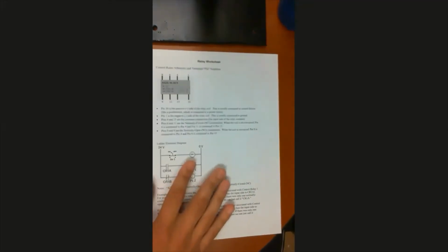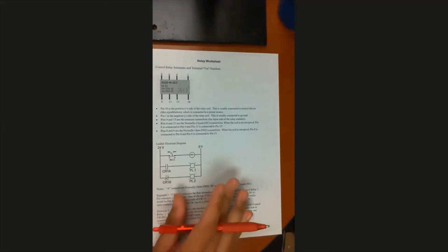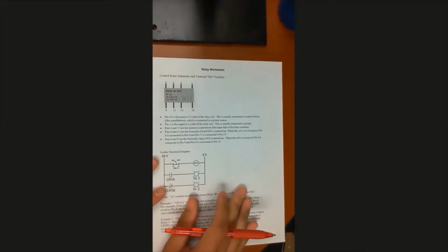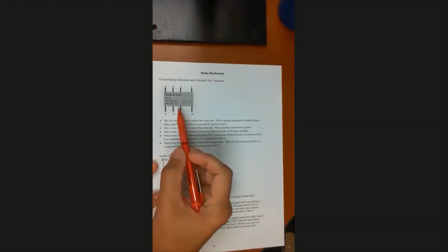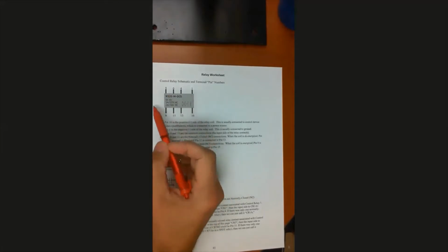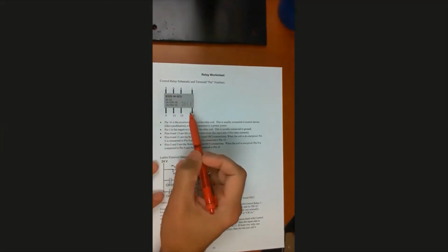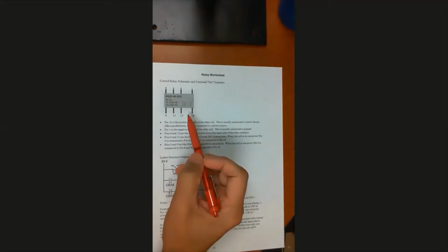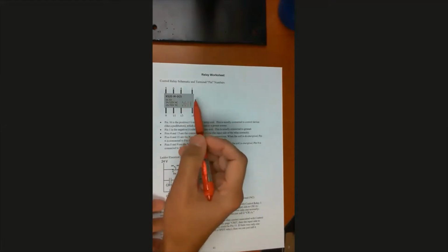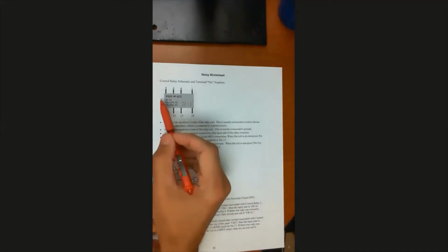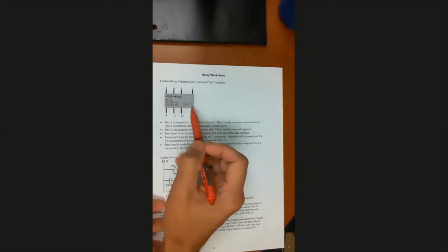All right, so this is page 41 of your lab manual. And the first thing that we need to make sure we're familiar with is the double pole, double throw relay in TinkerCAD. And this is pretty realistic. There are different kinds of relays. One is the ice cube relay that I showed before, but probably even more common in industry than an ice cube relay is one of these little prismatic relays that are like in a little black box. That's really what it is. It's like a little black rectangle.